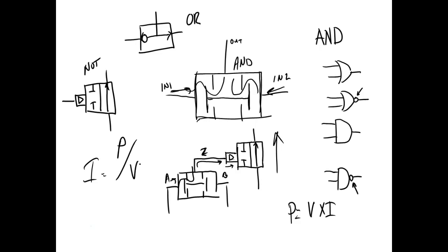Now, current is what sets the magnetic field. It's not the voltage. The amount of magnetic field you get has nothing to do with the voltage. It's how much current you push through a coil. So if they can lower that current, like I said, at 750,000 volts, how much current would that be? For 750,000 volts, I can send 750,000 watts of power with 1 amp of current, which means the magnetic field's not hardly doing anything. Right? You understand that? So how do transformers work?